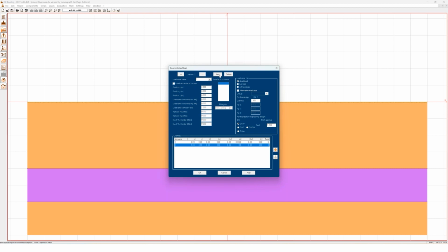Then we add a new load case, a live load. We choose this one here. And we have 20 kilonewton in y direction. And then we have 500 kilonewton and a bending moment of 50. And we have a category of office use.